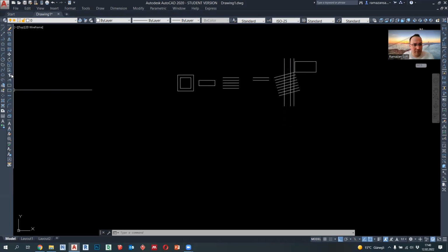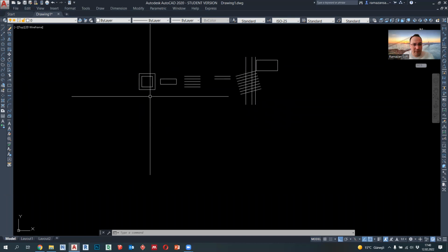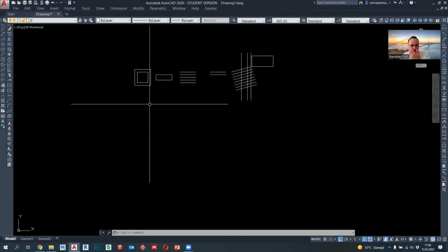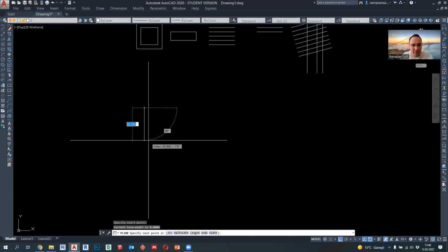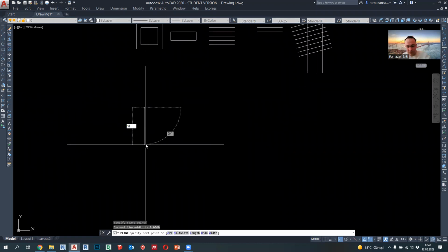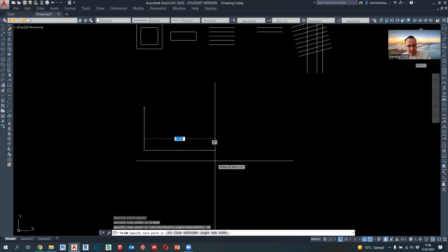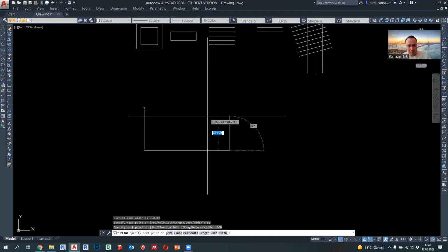We have covered the trim and extend line commands. We have used the copy command, mirror command, offset command. And lastly, we will make some exercises for you. Let's create a rectangle here, having 50 millimeter by 100 millimeter.